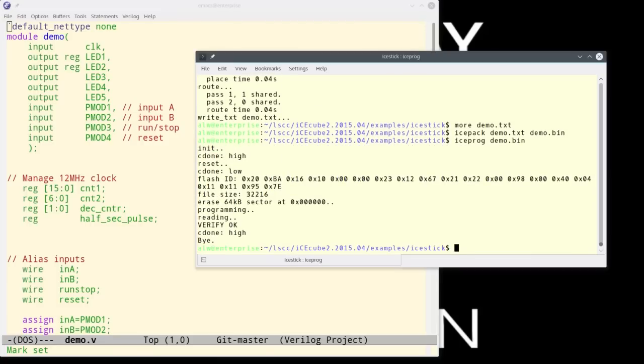And as you can see, it takes a few seconds and it programs the EEPROM on board. And then if you look at the actual device running, it's executing the Verilog that we gave it. Now keep in mind, just like we said in the first part, it's not really executing the Verilog. The Verilog described the circuits and described the interconnections, and all this process has done is map that into the primitive circuit elements that the FPGA has on board, and then did that configuration.